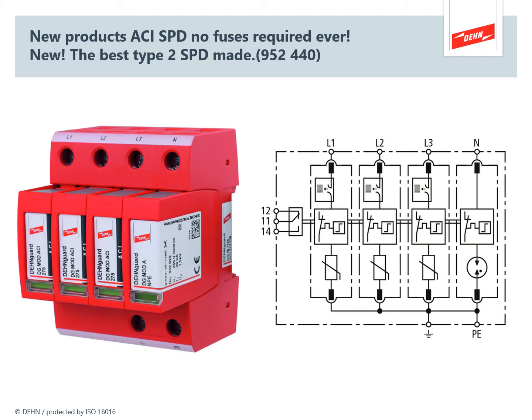Now we have some SPDs which have a component inside them which removes the need for having any overcurrent protection in the circuit surrounding the SPD itself. This technology is known as ACI, or automatic circuit interruption. When we look at the wiring diagram, if we look at the phase plugs L1, L2 and L3, what we have starting at the bottom of that arrangement is the rectangular shape with the line diagonally across it, and that's the MOV itself. That's the surge protection component.